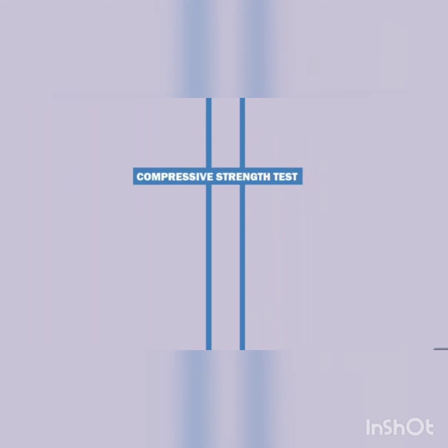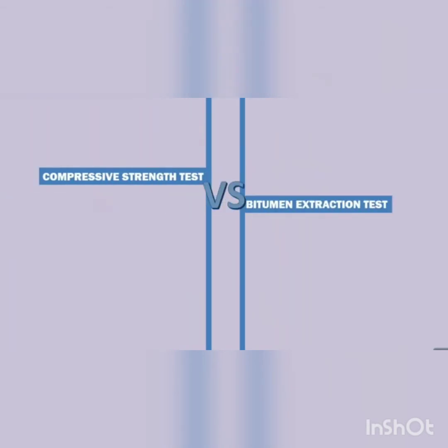So this test is parallel to that of the cylindrical compression test of the actual concrete samples, obtained at site before placement of concrete to determine its actual compressive strength as per the required mix design.